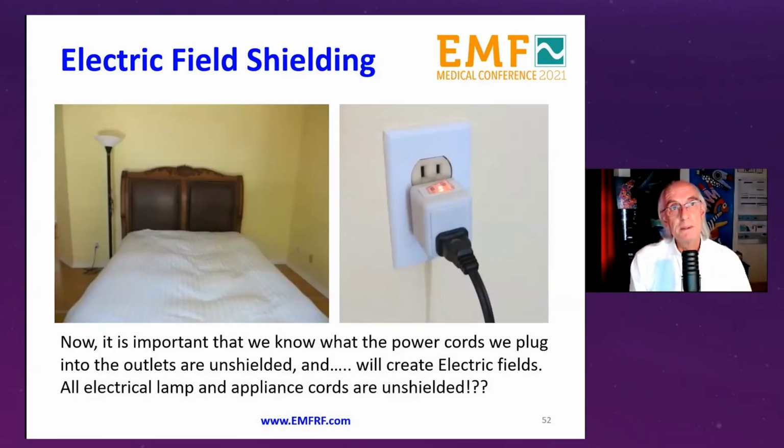Now there's another point to this. We have shielded the wiring inside the walls, but what do we still have? We have power cords to reading lights and any other appliances or alarm clocks or chargers or whatever you have. And almost all power cords we have in the United States are 2-pronged. That means they don't have a ground and they don't have a shield. In other words, I shielded my walls, but I'm still going to get the electric fields from the plugged-in devices. So what can I do about that?